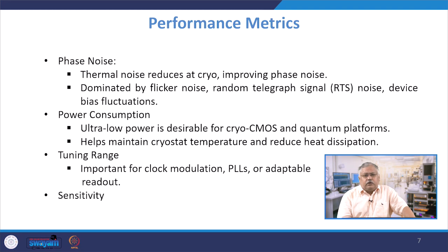Now another problem is that the oscillators which operate at cryogenic temperatures will showcase very large fluctuations in their parameters with temperature, and there are no mature device level models available at this stage to substantiate the changes happening due to temperature induced effects on the devices. So, that is a major challenge which you will face. Similarly, obviously the power dissipation is a challenge for all practical purposes in all cryogenic devices.